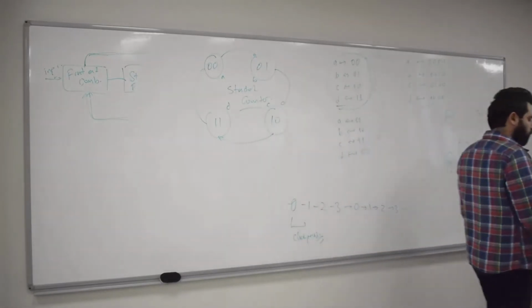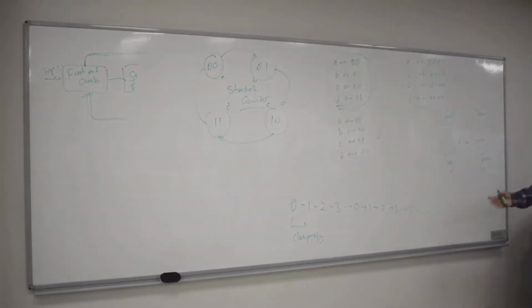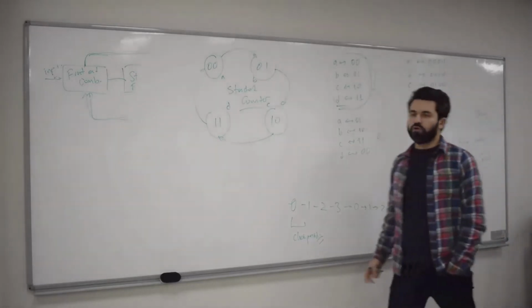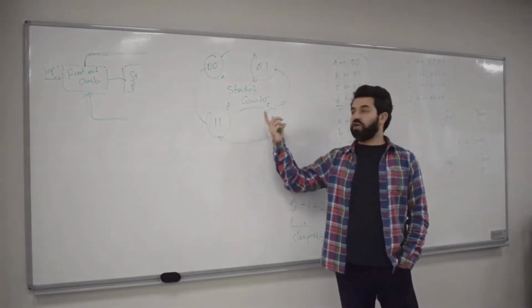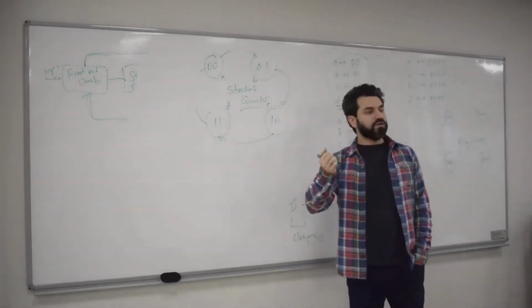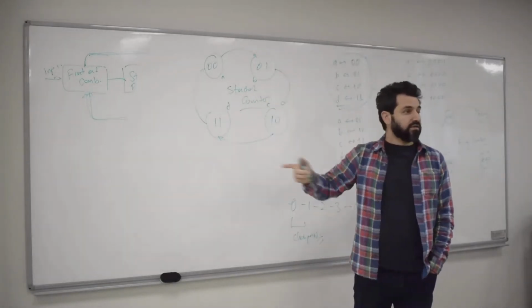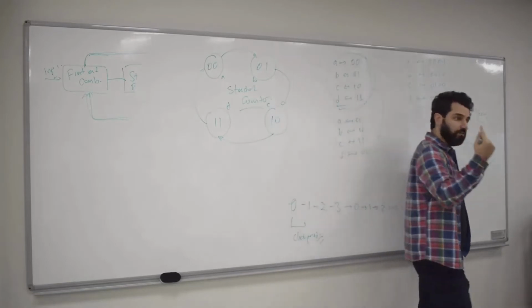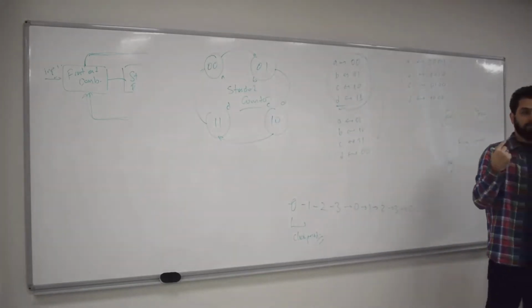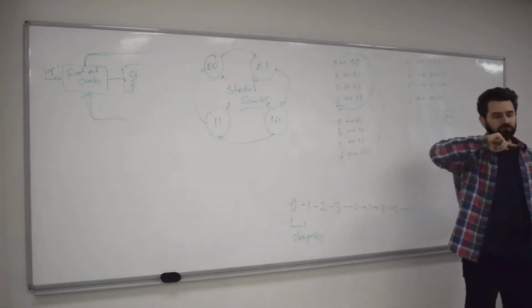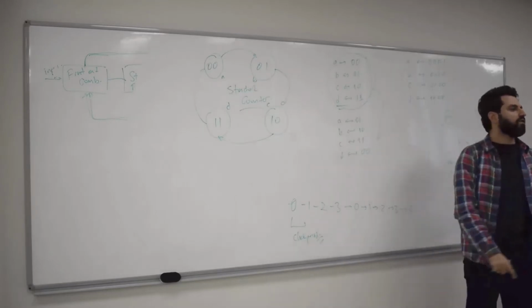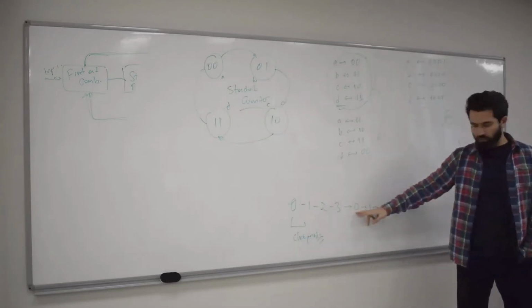And you can, of course, as I said before, introduce inputs and outputs to control this counter, such as an input, for example, to count forward and backwards, right? A single bit. If that bit is 0, we can let the counter count in the forward direction: 0, 1, 2, 3, 0, 1, 2, 3.